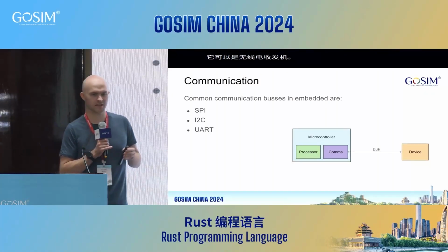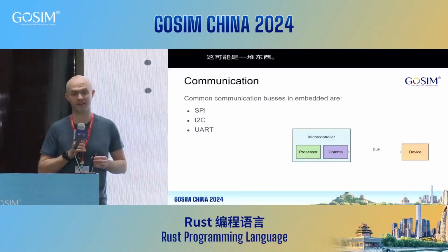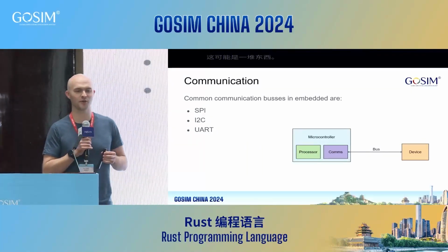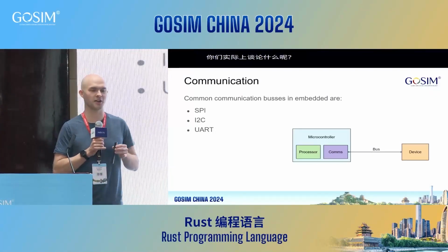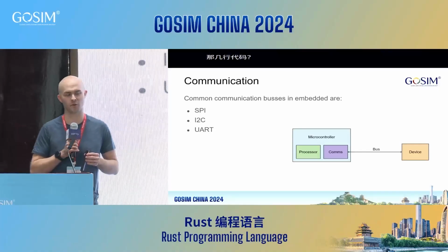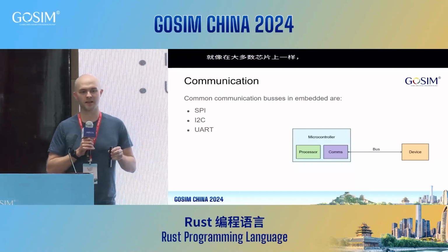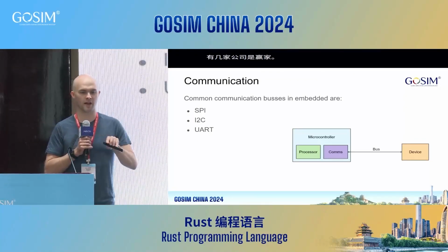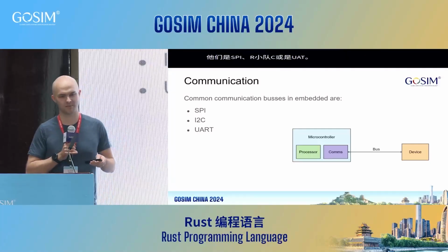So for communication, what do we actually talk over those copper lines? There are a few winners in this regard: most chips use these communication standards to talk to your microcontroller. They are SPI, I2C, or UART. So that means that the bus part of the schematic is one of those three, like 90% of the time.